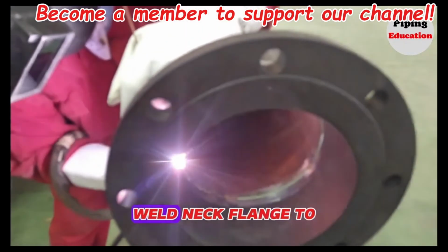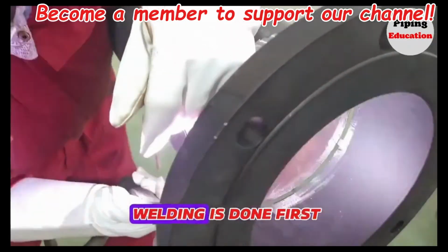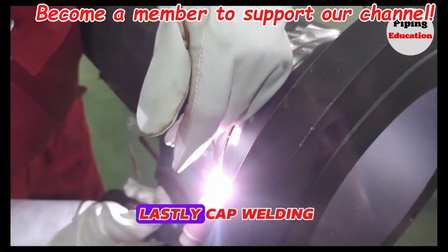Continue to fully weld the weld neck flange to the pipe now. In pipe welding, root welding is done first, then hot pass welding, then filling welding, and lastly cap welding.